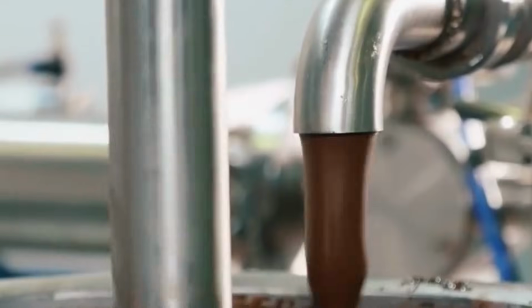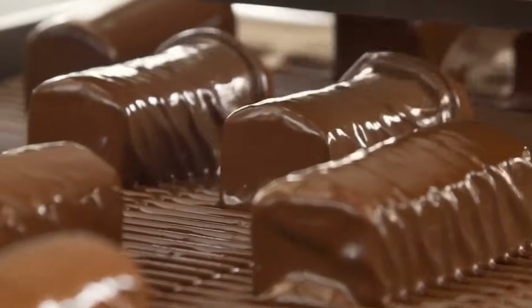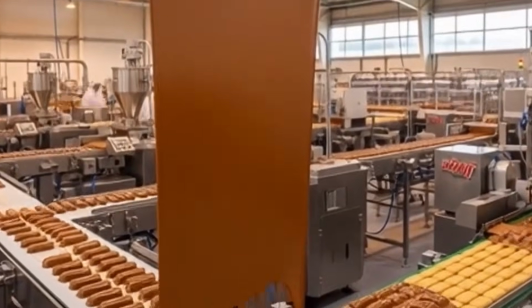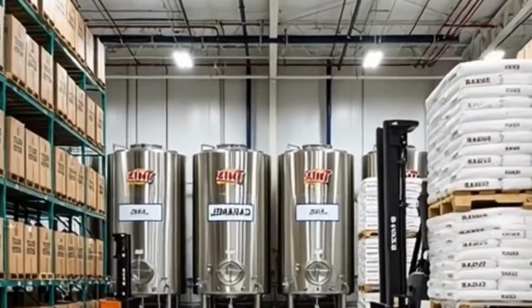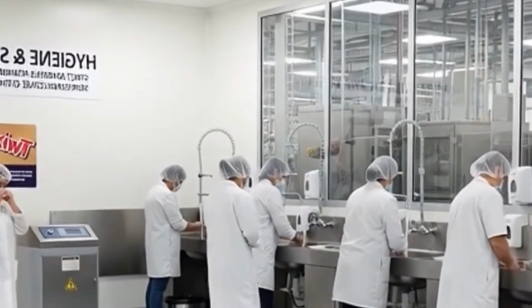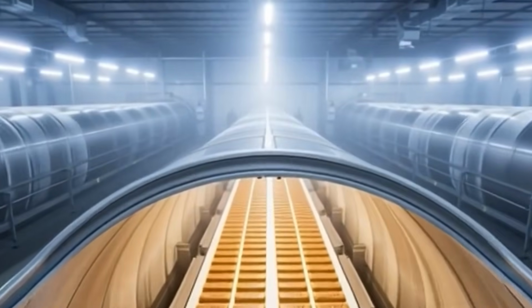Each caramel-topped biscuit is conveyed through a waterfall curtain of white chocolate. The enrober consists of a chocolate pump, curtain plate, bottoming pan, and vibrating removal section. The base of each bar contacts a submersion roller to ensure full underside coverage. A vibrating wire belt helps distribute the chocolate evenly, while an air knife system positioned immediately after the curtain blows excess chocolate off the top and sides to maintain uniform shell thickness.